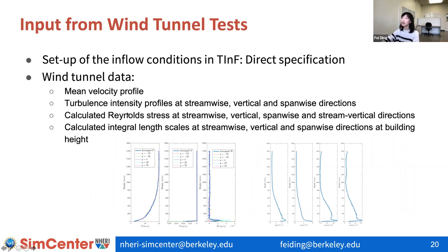And to use TInF to generate the inflow turbulence, we also need to know the parameters for the Reynolds stress and integral length scales. So those two quantities need to be calculated based on the data from the wind tunnel.